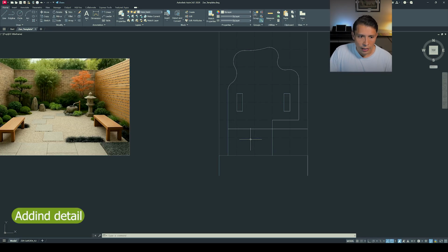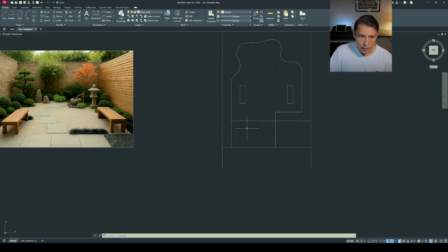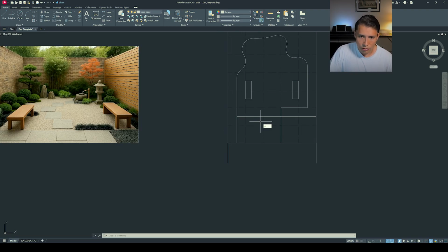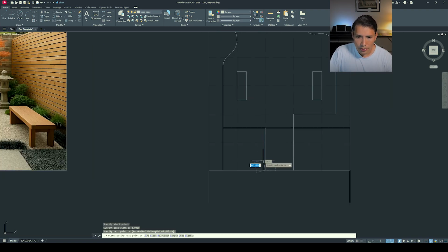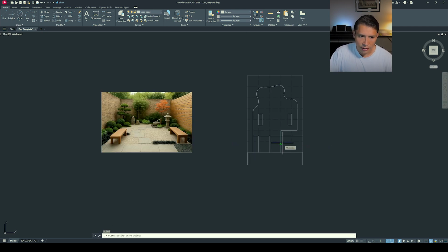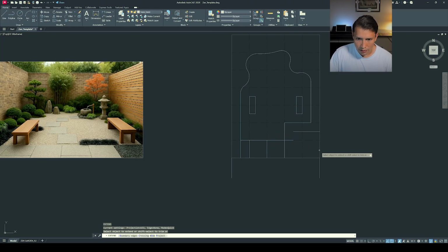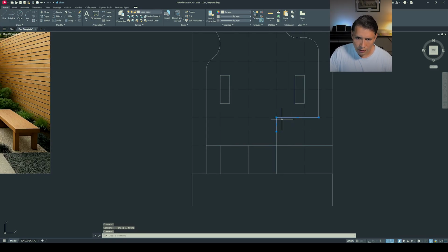We're going to start by drawing these stone pavings right here, and for doing that I'm going to just create a line from here, another line from here, and I think we need less hard surface on that bit, so we're going to bring back this line from this point up to this point, and I'm going to trim right here, and I am going to extend this up to here, then delete this line, and let's bring part of the planter 600 down, and let's extend this right here.